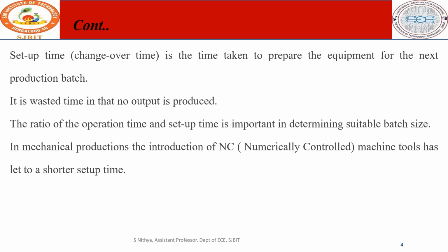The ratio of the operation time and the setup time is very important in determining the suitable batch size. To decide the batch size, we need the setup time and also the operation time. And in mechanical production, the introduction of NC, that is numerically controlled machine tools, has led to shorter setup times.